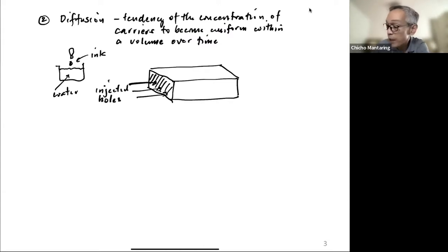Okay, there are many ways of doing this. One way of doing it is by heating this particular surface. So if you heat that surface, you're going to generate electron hole pairs, so you're going to have excess holes. No? Another way is through illumination. Another way later on is you're going to find is in a PN junction there's a minority carrier injection. No? But what will happen? Let's say I inject holes.